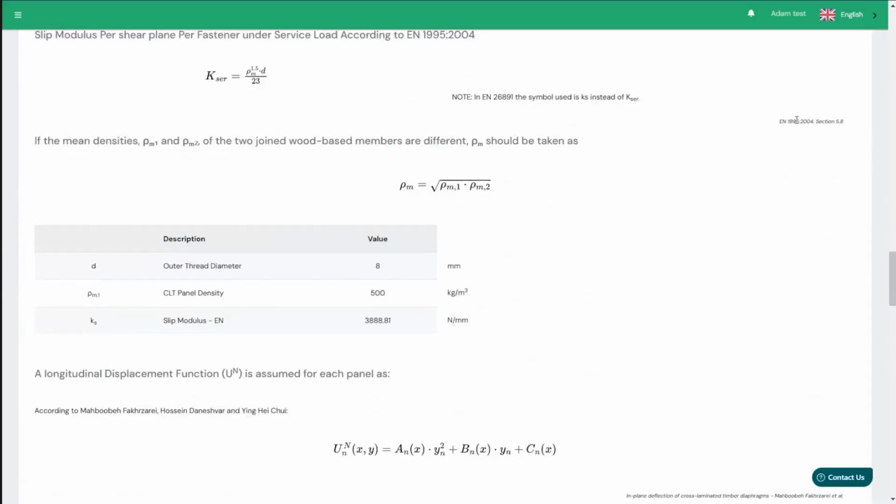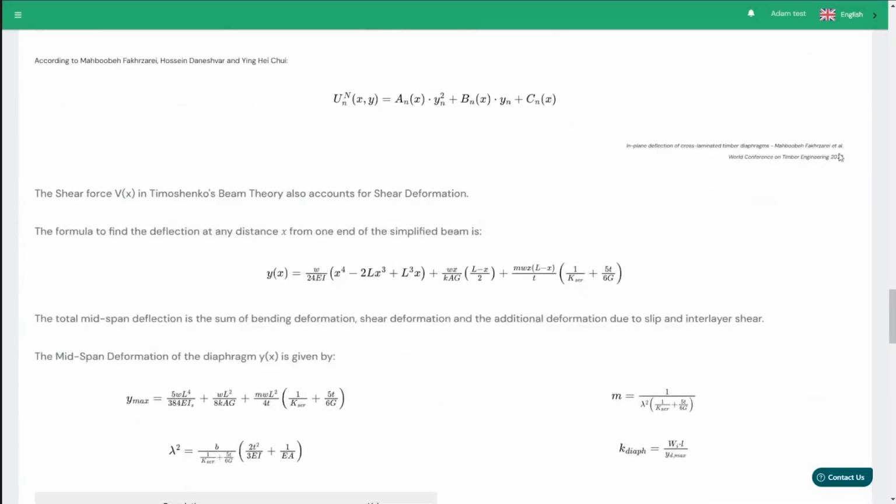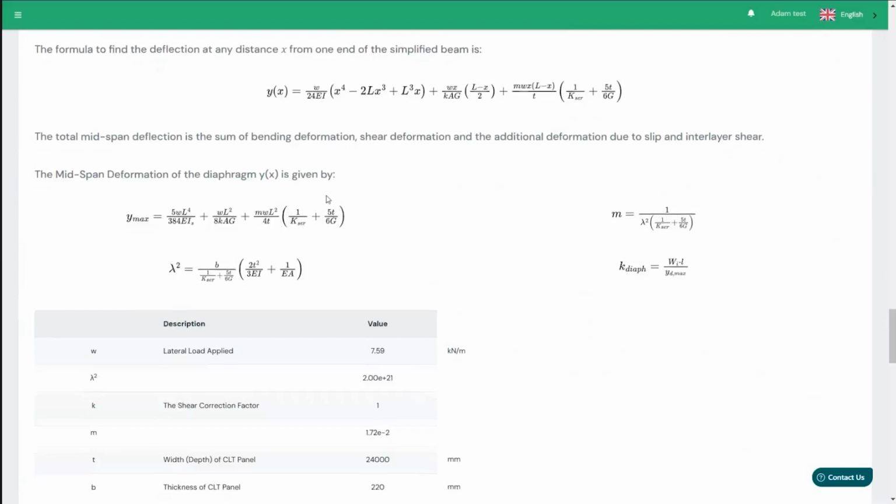So both of these being the same in this instance, the same panel, but in other instances, they might be two different. Yeah, moving through, you can see the equations. Again, not a black box, we follow it in full, but the equation that's familiar to you, what I showed before, is the panel stiffness, bending stiffness, shear deformation. And because it's a really deep beam, the shear deformation might actually be a bit more than, well, I probably originally expected when QAing this stuff. And then you've also got the connection contribution as well.